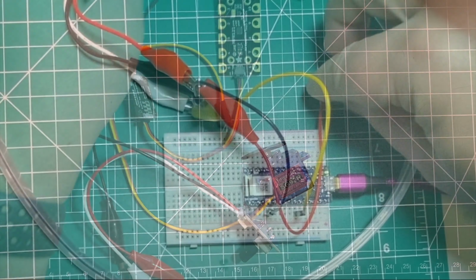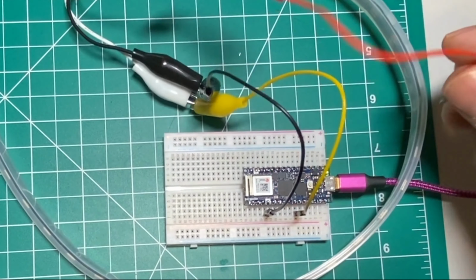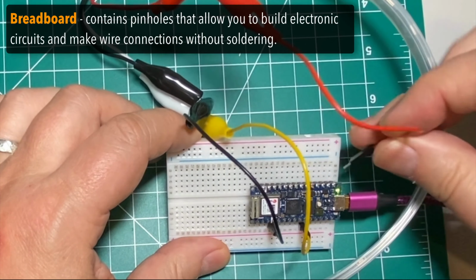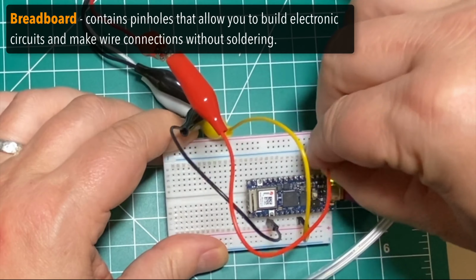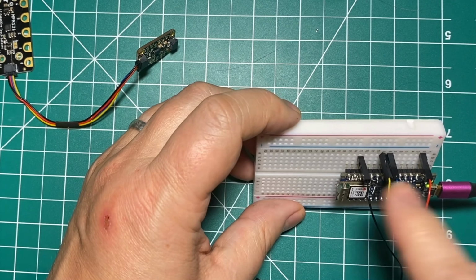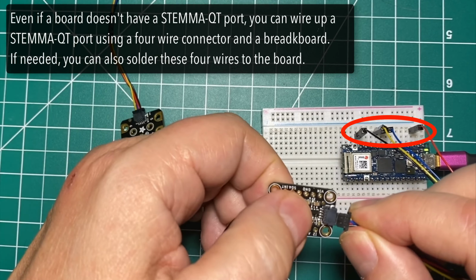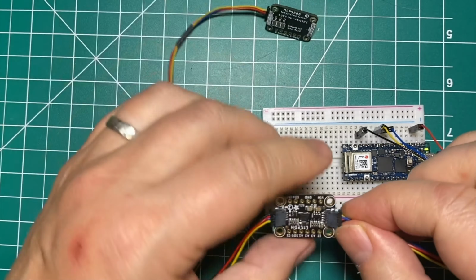Now, in most cases, you'll hook up 3-wire devices like this NeoPixel strip using a breadboard. I happen to be hooking this up using an Arduino Nano RP2040 Connect, but I could do the same thing with a Feather RP2040. Now, the breadboard is this plastic rectangle that you see here with the pinholes in it. You insert header pins into these holes to connect up wires so that you don't have to solder. Also note that even though the Arduino Nano RP2040 Connect board doesn't have a STEMMA-QT port for STEMMA-QT breakouts, we're going to connect one to the board using a 4-pin wire connection that has a STEMMA-QT port on the other end. I'll show you how to do this in a future video.